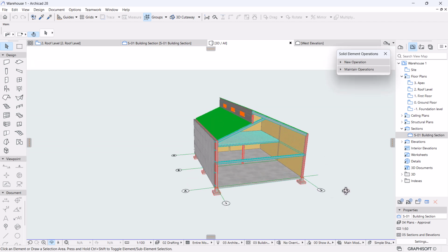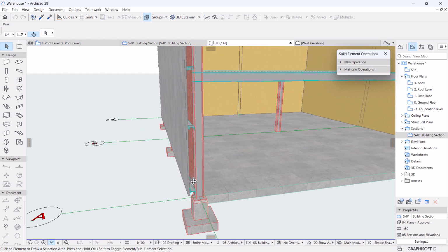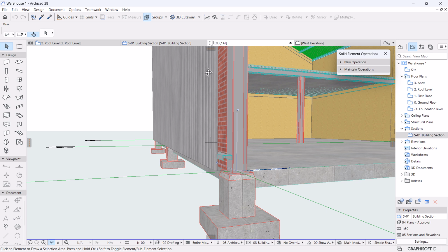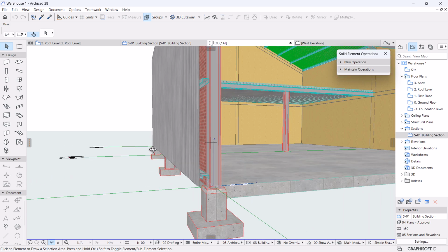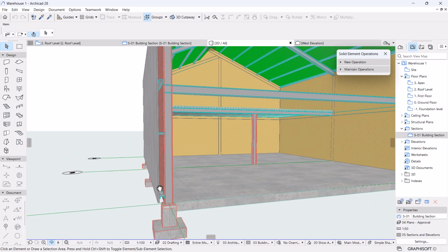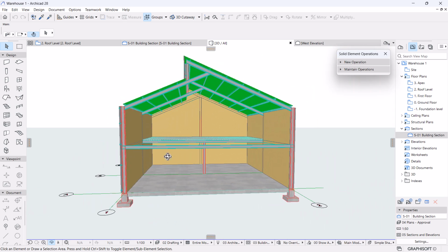Which is going to be the apron around the building. So basically the apron will be the one that we use to collect water that is coming from the roof and ease it out to the ground level. If you don't have it, you are promoting a serious problem between your structure and the ground. So you always have to have an apron that will have a gentle slope to move water away from the building. Otherwise it will seep into your foundations, and then your building will start experiencing some defects.